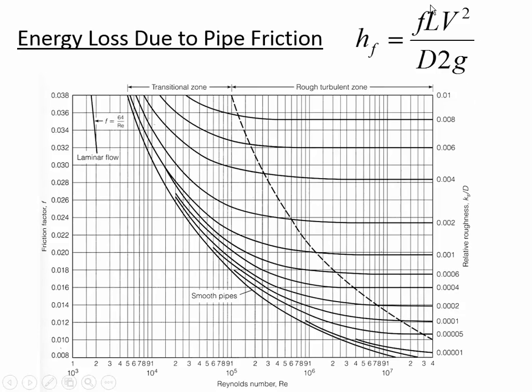So calculating this f actually is a real challenge, and when I'm teaching water resources engineering, we spend about 3 class periods talking about different ways to estimate the f value. You know, this graphical approach, the Moody diagram, is just one way. There's also formulas like implicit equations where you're solving for f depending on the velocity of the flow through the pipe and so on. And so just to remind you about an example that we've seen previously, one of the problems that we solved in class was looking at water flowing through a pipe that's connecting 2 reservoirs.